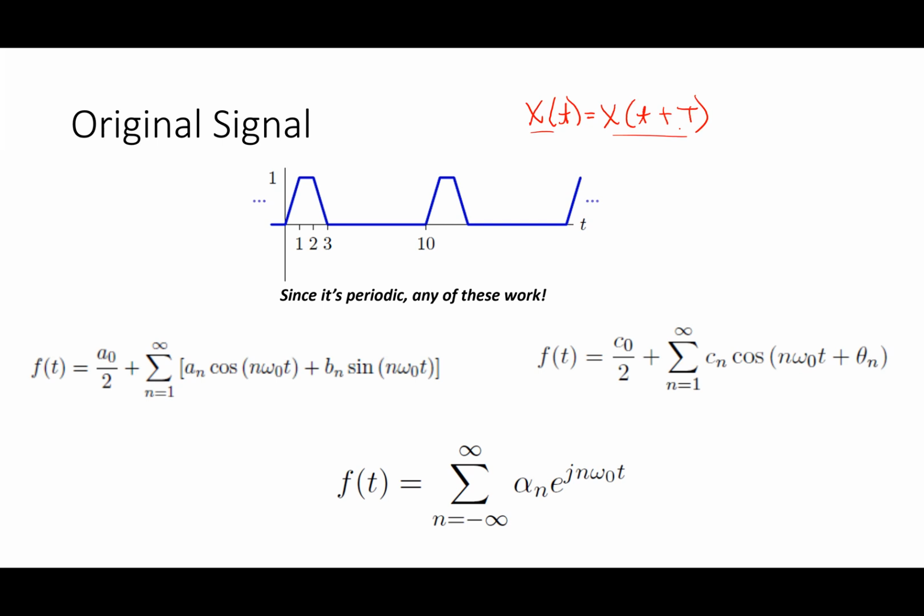So here's this periodic waveform, repeats on both sides, and essentially it is a sum of sinusoids. We can represent any periodic waveform with any one of these 3 representations of what I call the Fourier series. Either it's cosine and sine directly, or it's a cosine, or it's some combination of complex exponentials. So let me ask you this. Maybe let me make one more point first. Before I ask you that question, I say that all of these sinusoids are harmonically related to each other.